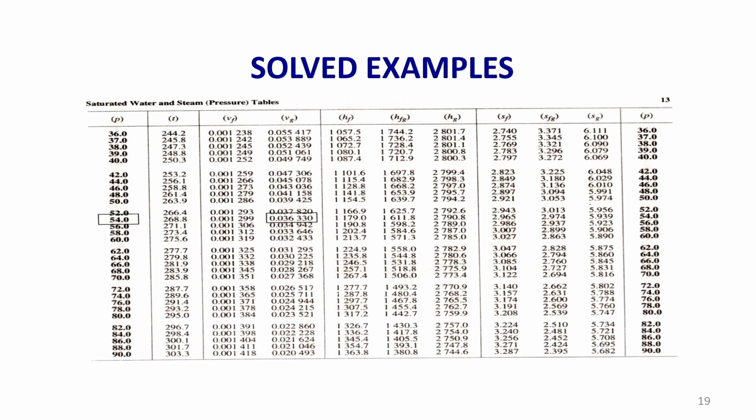If you see the steam table, this is table number 2. I have taken an approximate value only. The pressure is lying between 54 and 56, 54.6. Either we can take it for 54, which is an approximate one. The perfect value may be an average of 54 and 56, which will give 55. So, 54.6 if we round off, we will get around 55. Of course, I have taken 54. So, there will not be much difference in the answer.